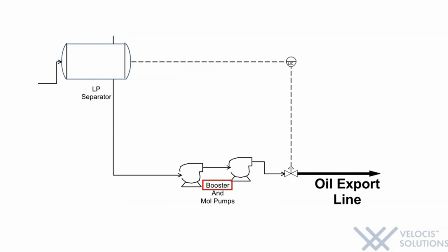Moreover, the bottom product of this column is the liquid which needs to be transported to the onshore for further processes or for a direct sale. As the distance between the offshore platform and the onshore terminal is huge, the liquid needs to have a certain level of pressure to overcome the sum of pressure losses on the way and the pressure at the entering point. This pressure is generated with the help of two consecutive pumps.